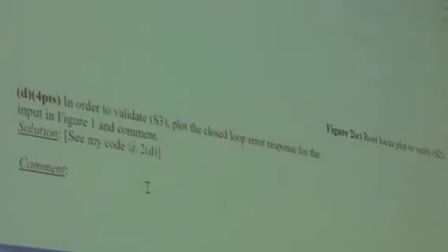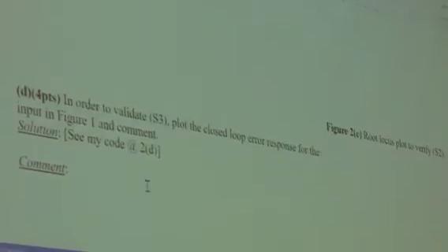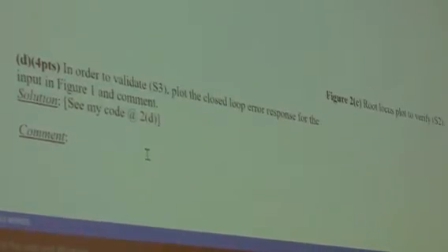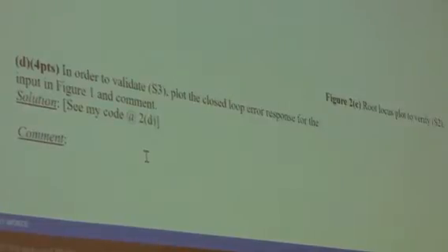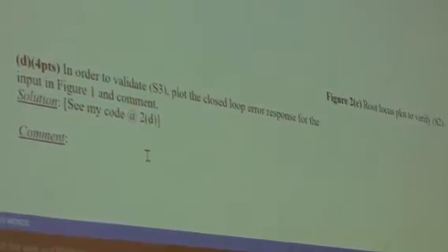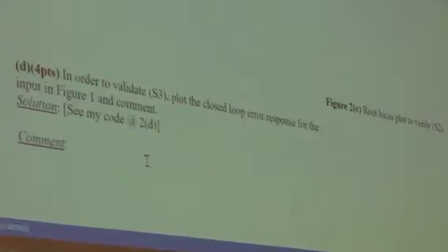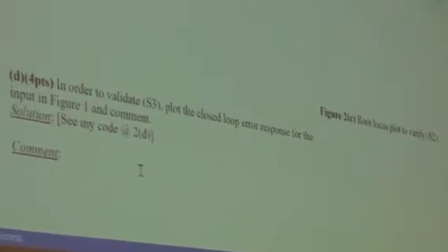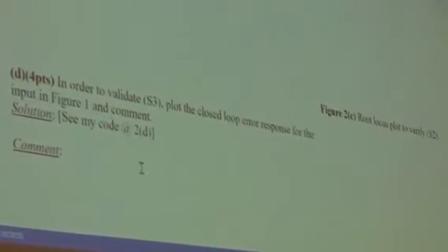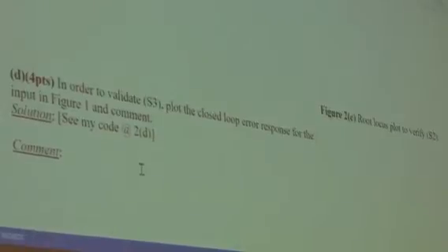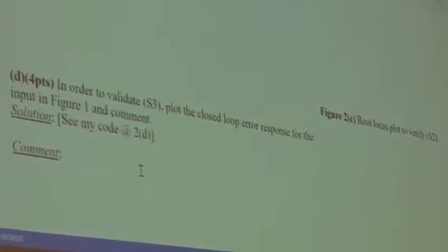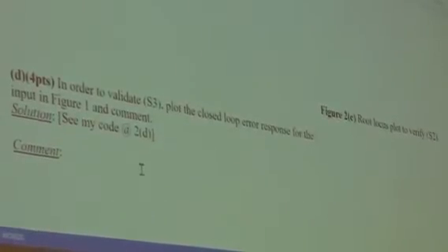All right, and then comment. Does it validate? Is spec 3, the steady state error spec, validated? And this is direct feedback for you, because if you get to this point and you run LSIM with that input, and you get over 1 degree steady state error at that high rate of gamma, that high gamma slope, something went wrong.